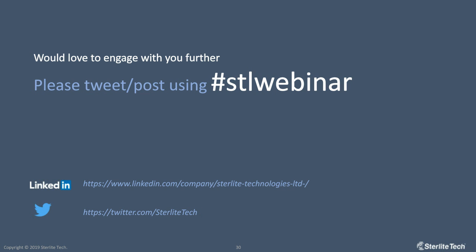Yeah, absolutely. This goes back to the point about surveying and looking at what assets you have. Leveraging existing towers, light poles, pick an asset that you want and look at leveraging that. One important aspect of this is getting enough height on these to clear the clutter, so you have line of sight, especially for the millimeter wave and the higher band technologies. So it's a tough choice. Again, that's where the survey comes in, and you survey everything that's around to be able to provide that capability.